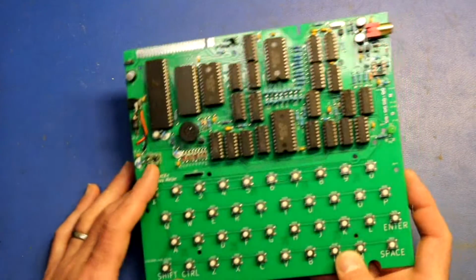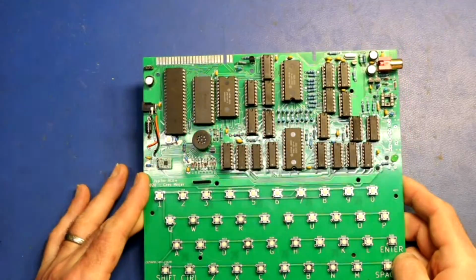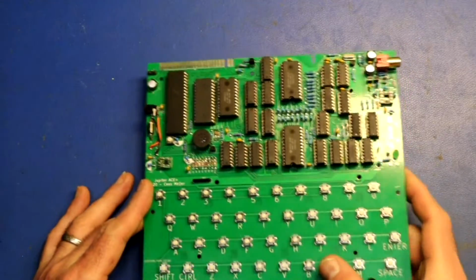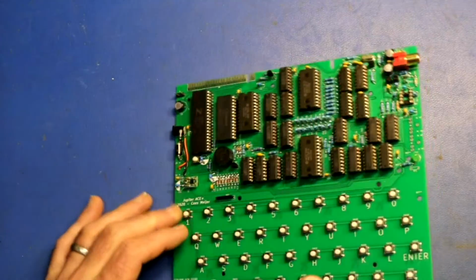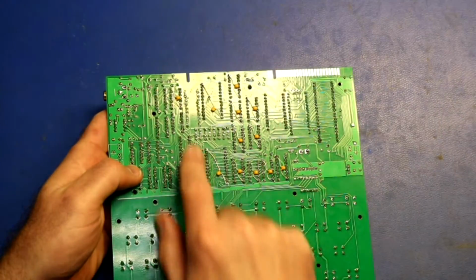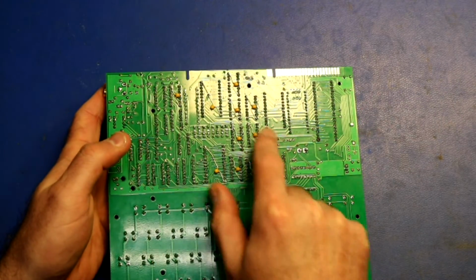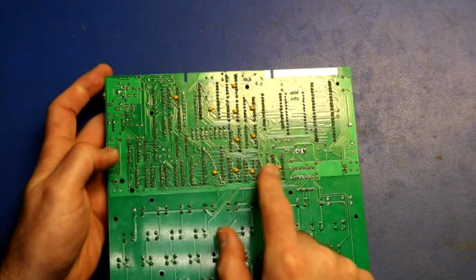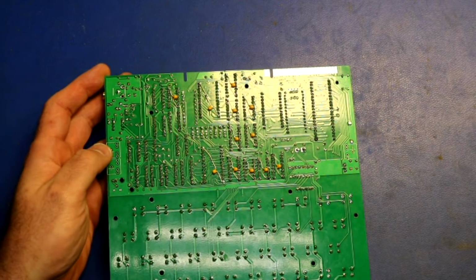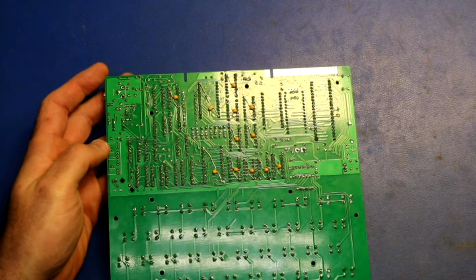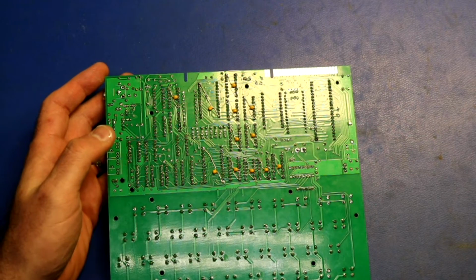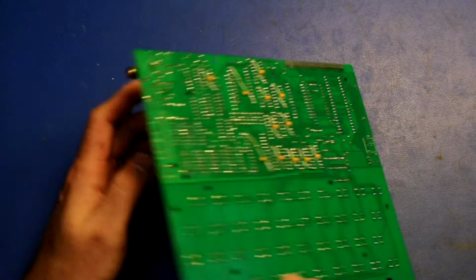Then I noticed that this thing is almost completely devoid of bypass capacitors. So for my last shot in the dark, I stuck bypass capacitors around all of the ICs that were around here in the video RAM and character generator RAM area, including the 2 static RAM chips. But that also yielded no change in behavior.